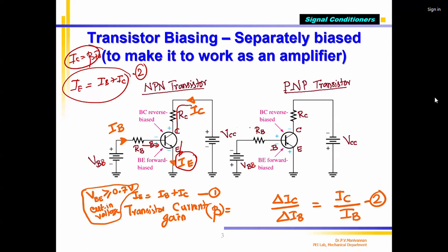Another thing, I told you, if IB equal to 0, for example, this is BC107, beta equal to 100. I am supplying VBB equal to 0 volts. What is my IB? 0 divided by this RB. RB I said 1000 ohms. So automatically IB equal to 0.